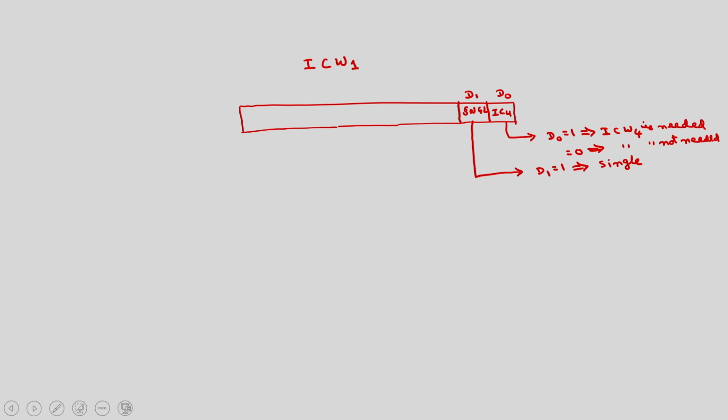As I have discussed, this 8259 can operate in single mode as well as cascaded mode. In single mode, 8 different devices can be connected to the 8259, whereas in cascade, 64 devices can be connected. I will discuss how the 8259 will be cascaded to service 64 different IO devices.